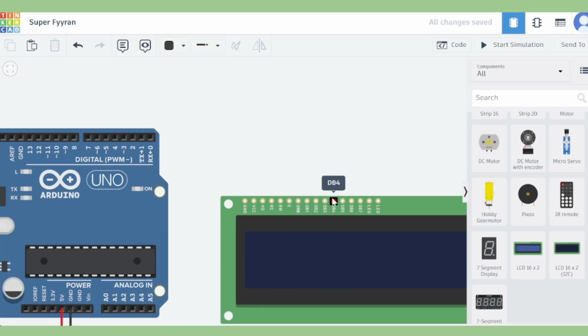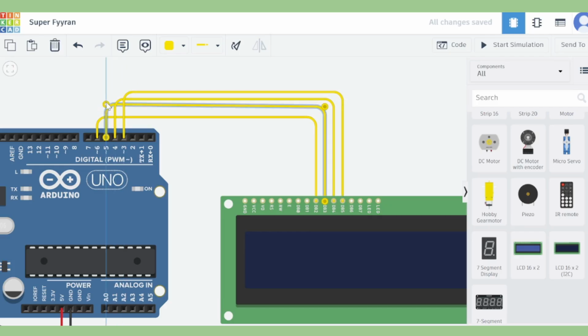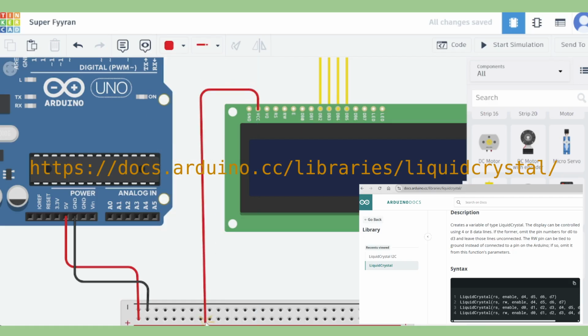The first one is the basic type. This is an earlier configuration where the LCD has a 16-pin pinout. Among them, 10 pins are related to data transmission, but in practice, this can be reduced to as few as 6 pins. For programming, I referred to the LiquidCrystal library.